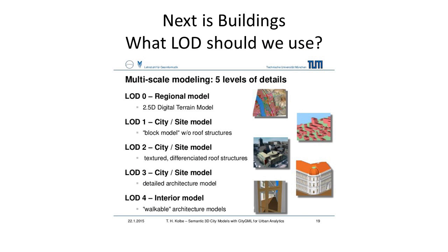Okay, so when you're building up your buildings, what level of detail should you be using? There's a number of different levels out there, whether you're going 0 to 4 or 1 to 4 or 100 through 500, it doesn't matter. For us, from a maintenance standpoint, we're just looking for really block representations. We don't have to have photorealistic buildings. We would like to go more than just the extrusion of the footprint of the building, so that's an in-between state. We would like to see roofs if possible, because we've got roof maintenance that we have to do. So we're shooting somewhere between a high 1 and low 2, depending upon what information we have to put into the model.